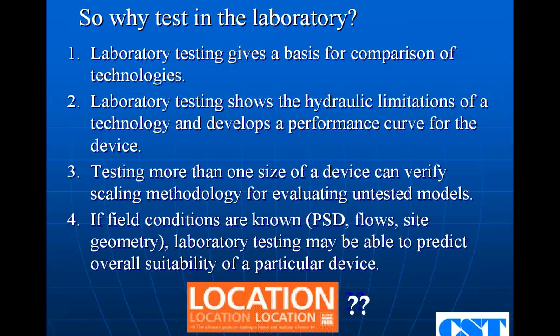So why do we test in the laboratory? Well, as I mentioned earlier, it gives us a basis for comparison of technologies. It is, however, interesting to note that if you examine the NJDEP data and the ETV data, those devices which tend to catch 80% of, let's say, an average 90 micron mix of particles, all tend to hover around 20 to 25 gallons a minute per square foot. So laboratory testing also tends to support that. It shows the hydraulic limitations of a technology.